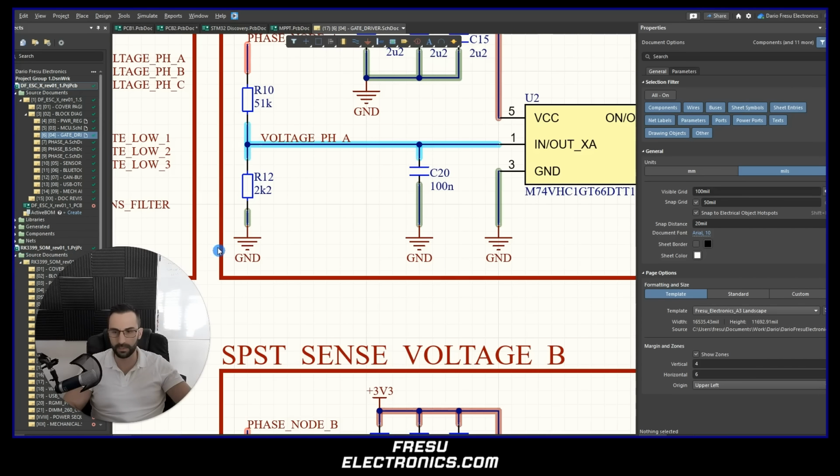But then we have to think about this, which is the return reference plane. So the return reference plane is called that because it's used by the return current, but also by the voltage. So by the return current because of the loop. So we have this loop in here where the signal goes, reaches the load, and then it comes back. So not only does the signal go, but it has to come back to the source. So this is the part of the return. Now the part of reference. Why do we call it reference?